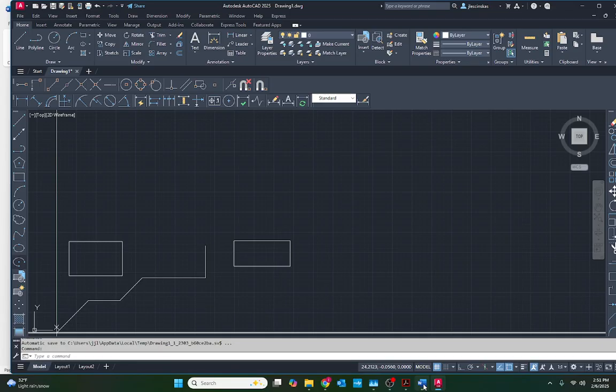So let's take a quick look back here. We are at lines. Let's talk about how you select things. You can do selections as follows. First of all, you can just click on something to select it. The second is to use the select window. Before I show you, let me point out that this is different than virtually every other Windows program. To create a select window, you simply press and release the right mouse button.